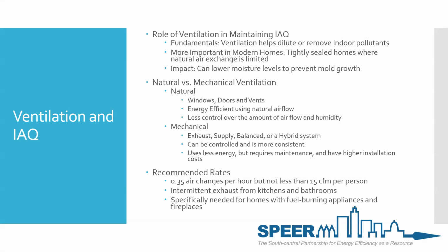You don't know. Mechanical ventilation is exhaust, supply, balanced, or I've put here a hybrid system. There are companies that make hybrid systems that are just a supply or an exhaust only, but have an additional controller that can control bath fans or kitchen exhaust to balance the home itself. So when it comes on and pushes air into the home, it also exhausts air at the same time, allowing it to be a balanced system, a hybrid ERV, if you would. These can be controlled. They're way more consistent. They use a ton less energy by comparison to the air handler. They do require maintenance, and there are higher installation costs.